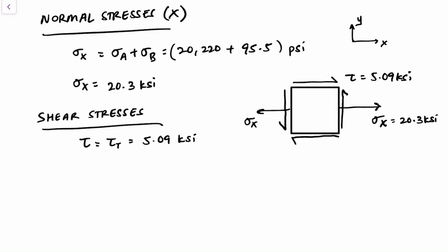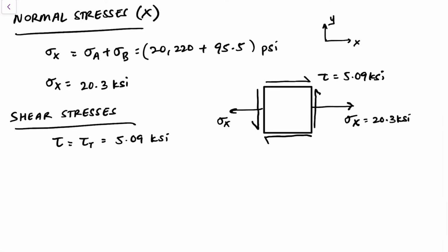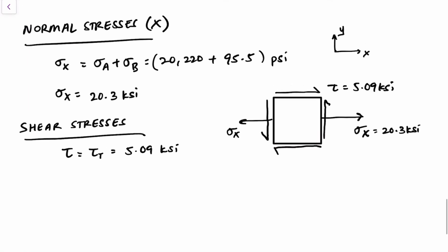And we call this uniaxial shear loading, right? Biaxial means there wouldn't be any shear, but there would be a sigma x and a sigma y. And the reason we have no sigma y here is because there is no axial or bending stress in the y direction, which means that your elements don't compress or elongate in the y-axis. Okay, so that is part B.